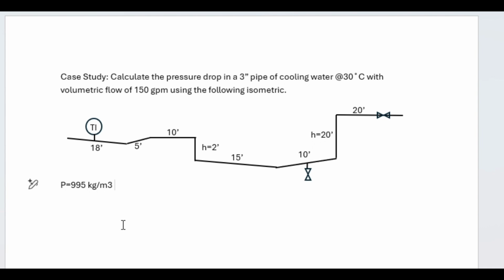temperature doesn't matter this much, but viscosity is very important, so make sure that you have the right viscosity at the right temperature. Viscosities change a lot with temperature, and viscosity matters because it's very hard to pump viscous material.